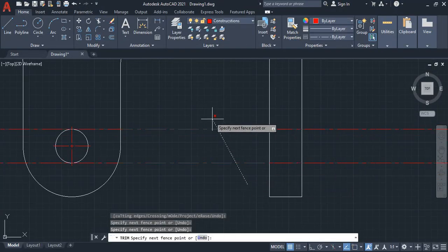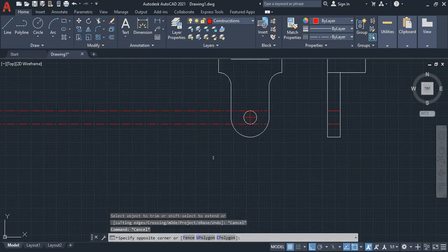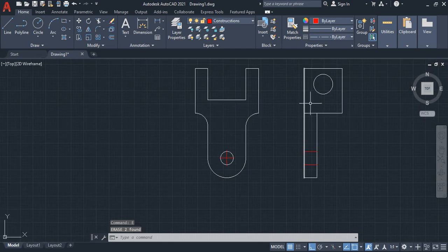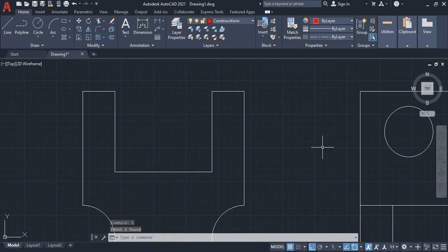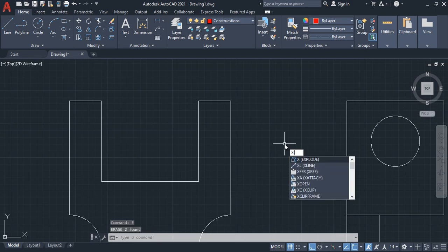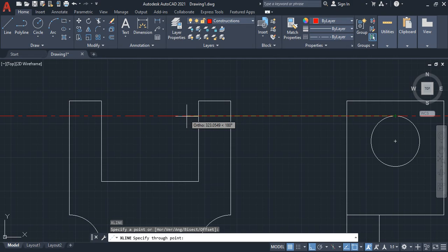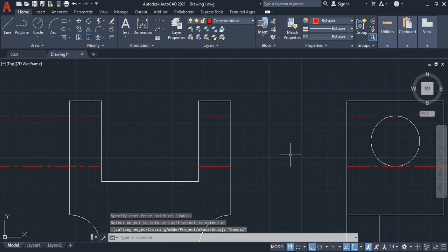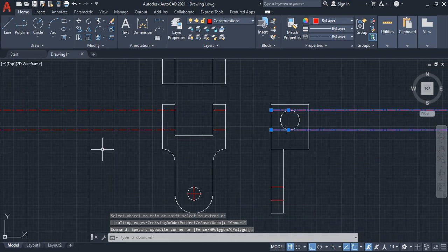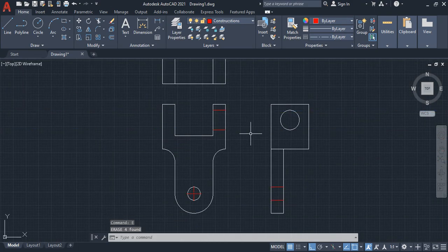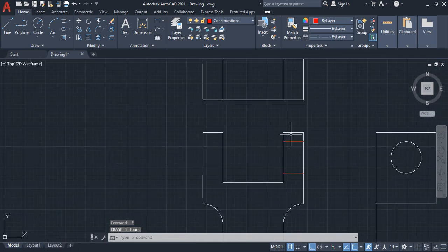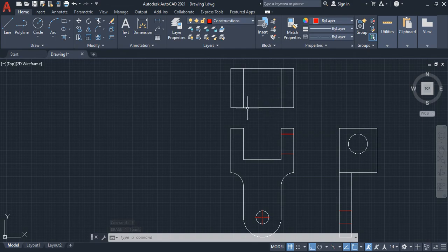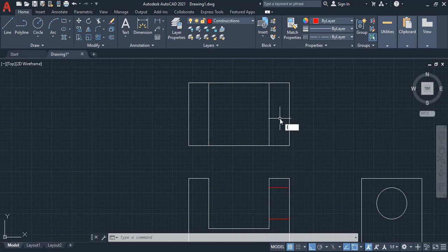Now trim, okay. Auto trim, erase the unnecessary lines, and we want to add 2 more XL lines like this. Now trim, okay. Erase, is fine. Since it is a top plane, we need to add 2 lines.